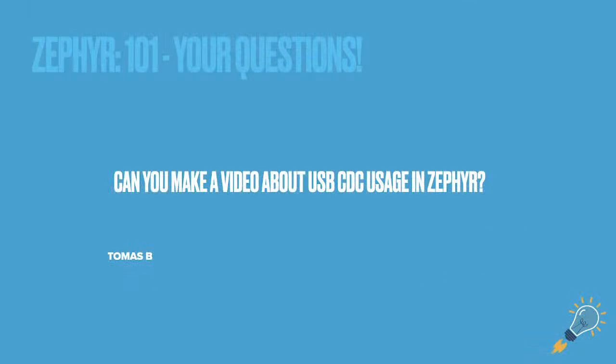But yeah, we can definitely talk about setting that up on the nRF52. When I talked about this in my Zephyr talk, I actually enabled some USB CDC stuff just so I could test it out, because I was using it before for console-y debuggy things, but it wasn't working 100% right. So in this case, I've worked out all the kinks and was able to get it working on the air quality wing setup that I had before.